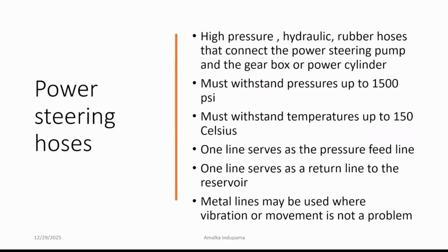Yes, and power steering hoses should be sufficient to withstand higher pressures up to 1500 psi, and temperatures up to at least 150 Celsius.